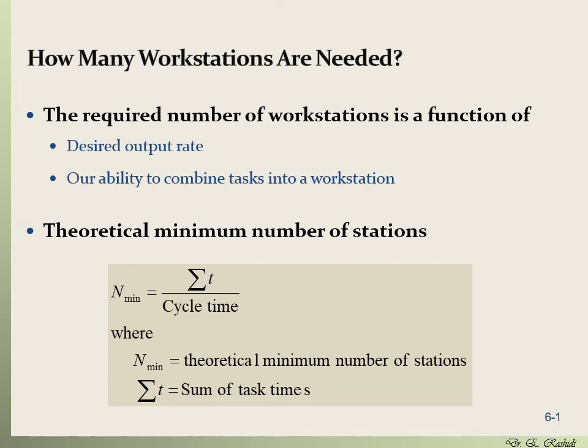How many workstations are needed to balance a line? The required number of workstations depends on several parameters. One of them is the desired output rate, what you would want the output rate to be. And also our ability to bundle up tasks and put them in a workstation. These are the two main parameters here.